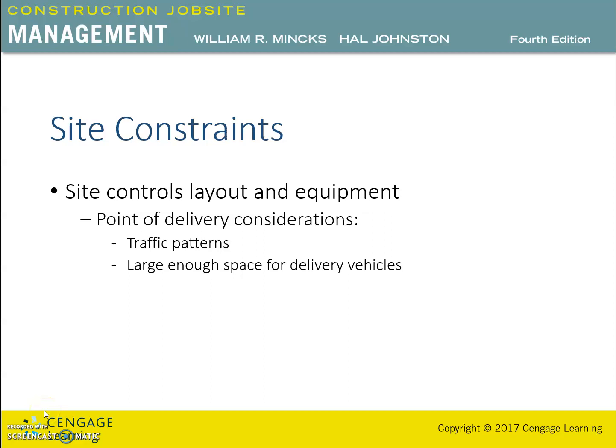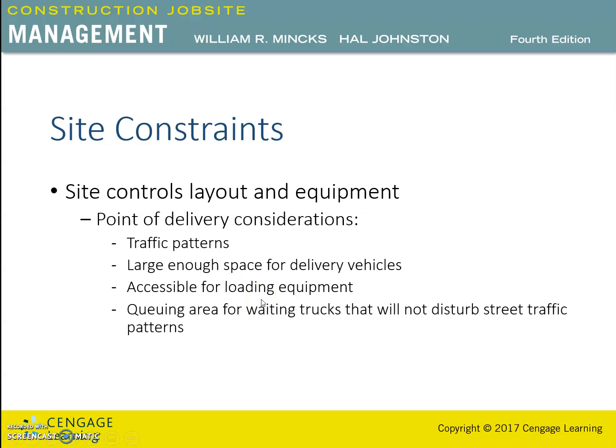In the last video clip, we were talking about the site constraints. We can say that the site controls, layout, and equipment should be done in such a way that the site should be accessible for loading equipment. The queuing area for waiting trucks should not disturb street traffic patterns, a concern particularly with concrete ready-mix trucks, where trucks need to follow each other closely to avoid interrupting the concrete pour.